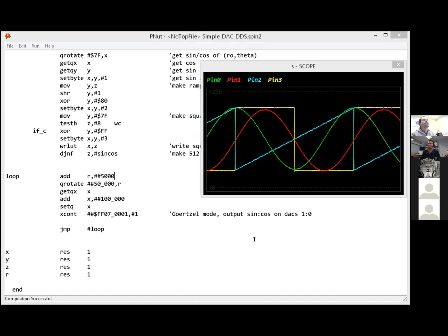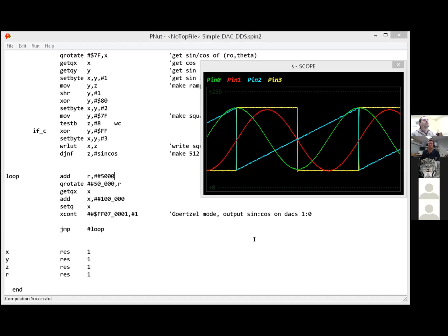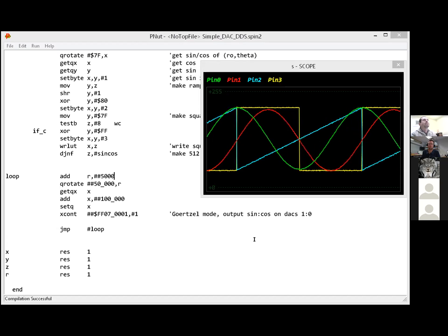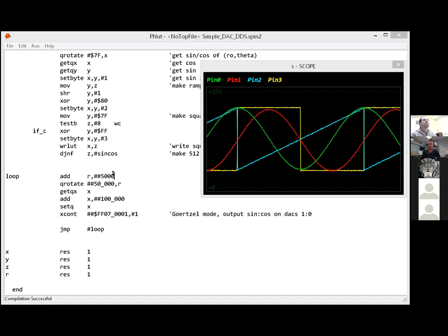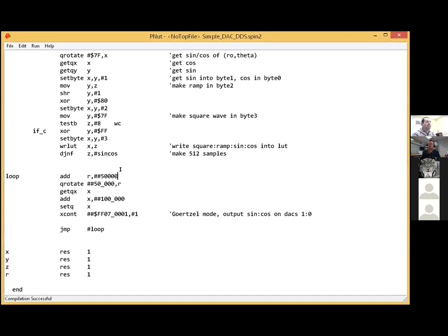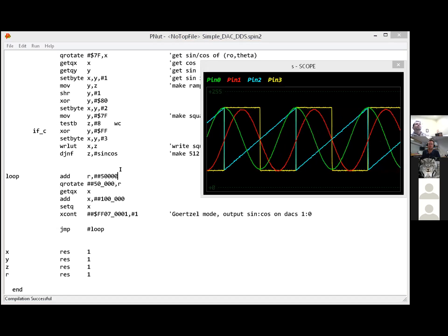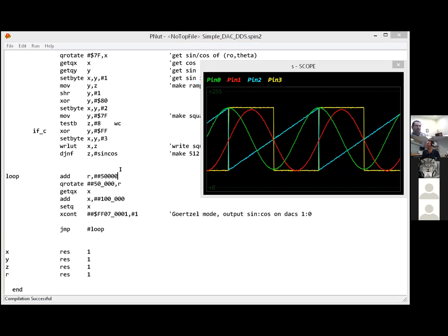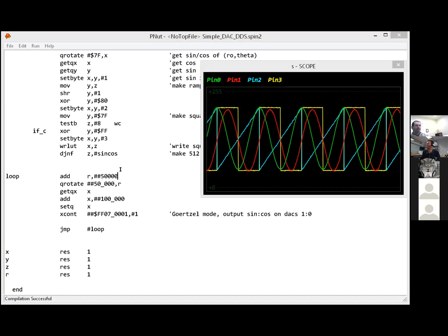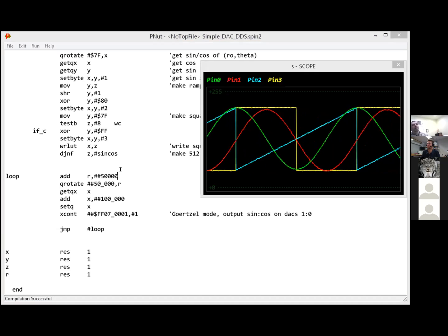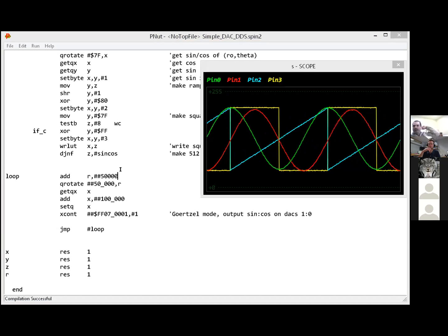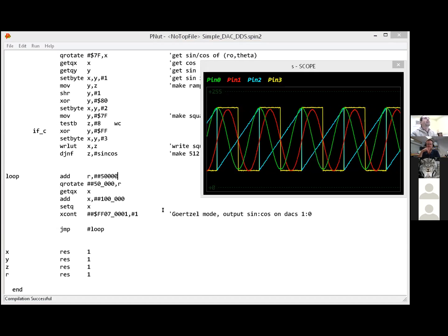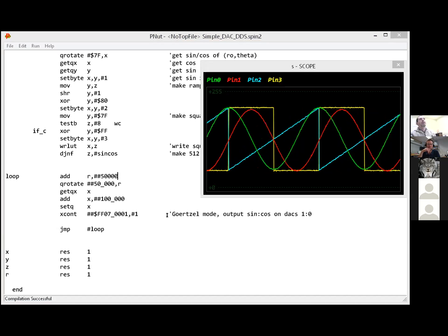You could also fill the LUT with a different piece of code to make the waveform change over time as well, right? You could just constantly update the LUT with a wave shape, and the streamer will be outputting it to those DAC channels for you. Yes. And there's also a color space converter. I want to show one other thing. Any more questions on this?